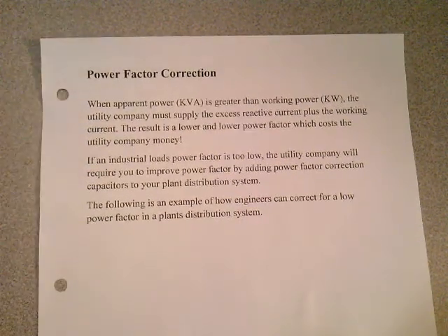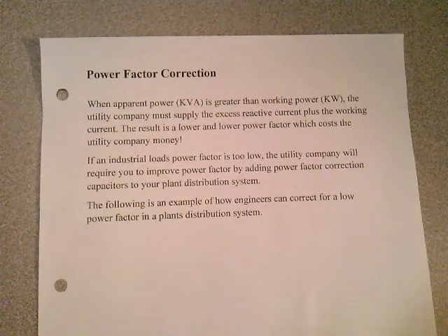Remember how power factor works. Whenever you have a lot of resistive load compared to reactive load, the power factor approaches 1. Whenever you have a lot of reactive load compared to resistive load, the power factor approaches 0. So the power factor falls somewhere between 0 and 1. It's just a number. So a lot of manufacturing facilities have a lot of motors, a lot of